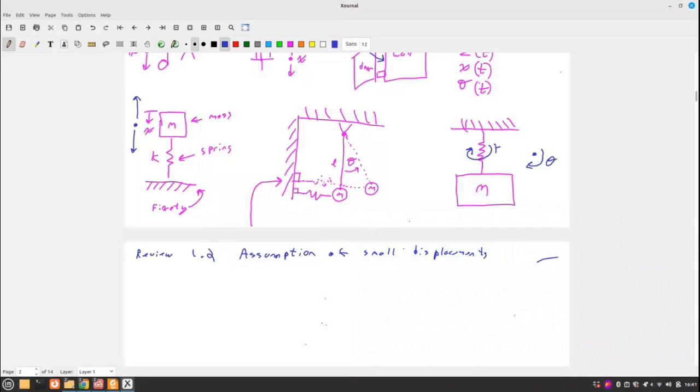And then we would have K, which is our stiffness of the spring, subscript theta to just show it's a rotational stiffness. And we're trying to spin our mass, right? And if we do that, the value of importance there might not actually be mass. It might be our polar moment of inertia, J, right? Because that's what's going to resist the rotation. So all of these are valid 1 degree of freedom systems that we could talk about through the course of the class.